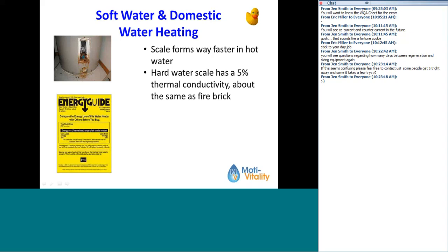Well, that's the same thing that happens when you have scale buildup on the heating element in the water heater. You've got to heat that rock up first before you can get to the water. And so obviously it's going to take a lot more energy to heat the water through that fire brick, essentially, than it does without it.